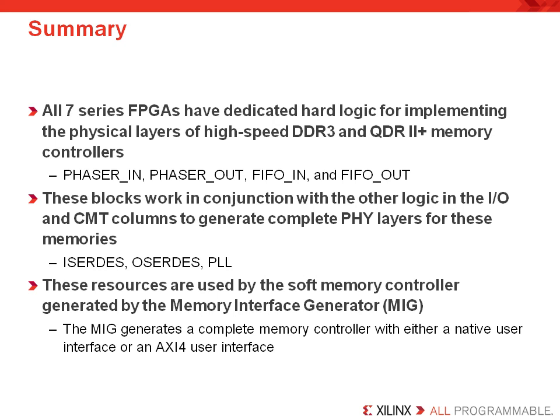Now, these logic resources will work with other logic in the I/O as well as the clock management tiles columns to generate a complete physical layer for these memory controllers. This includes resources like the ISERDES, the OSERDES, and the IOBs, as well as your PLL, which is in the clock management tiles. Now, all these hardware resources are used by the soft memory controller generated when you build it with the memory interface generator. So it does all of this work for you. The MIG will generate a complete memory controller with either a native user interface, or it can also be customized by you to use the AXI user interface.